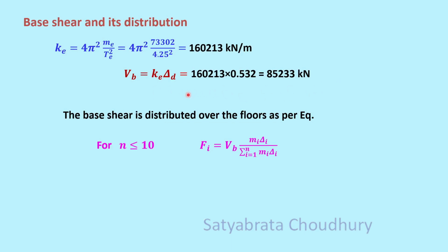Now you see, in force based design also you get a base shear through the code, and in displacement based design also you are getting a base shear here. What is the difference then? Both are forces. In the code based design you get that force through only consideration of forces, acceleration, etc. Here you are getting this base shear by considering a displacement, and this displacement corresponds to the design point where the stiffness also corresponds to Ke. So you are now getting a base shear which is compatible with your desired displacement parameters.